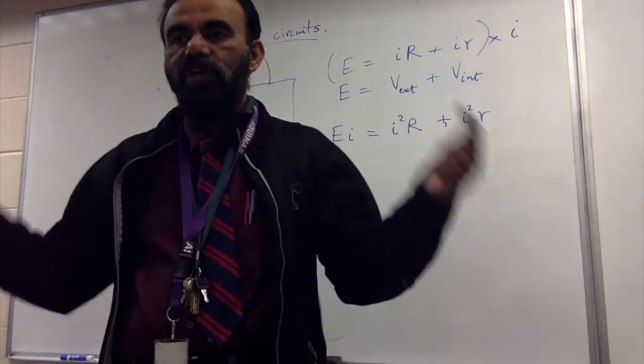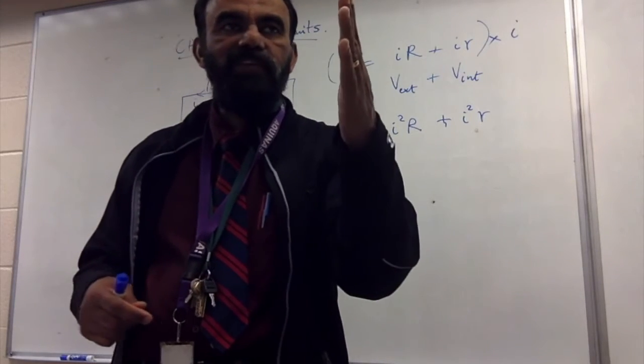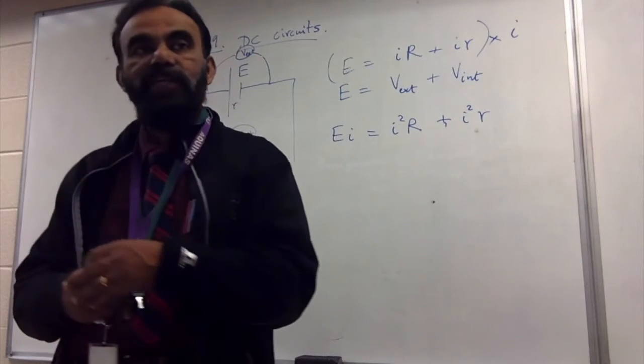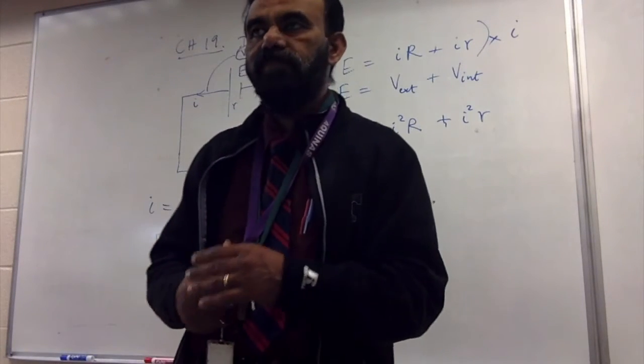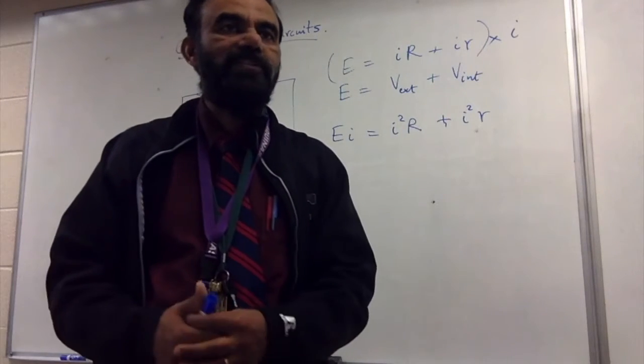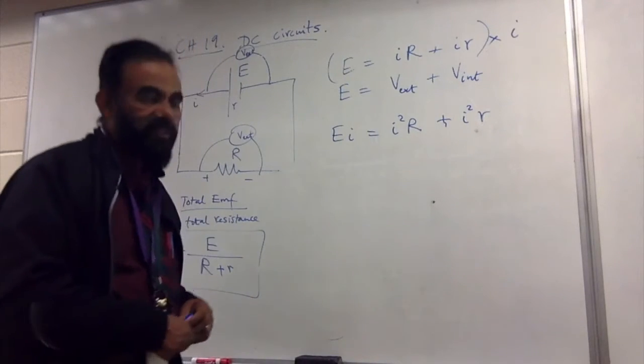Okay. Now, when you recharge the car battery, lead sulfate changes back to lead, and the other lead sulfate changes back to lead oxide, Pb and PbO2. And once you do that, the car battery is charged up. So it will have the right voltage, and it will have low internal resistance.